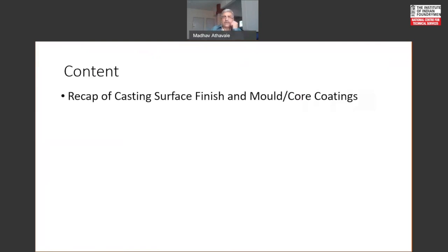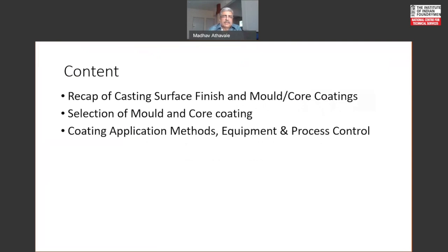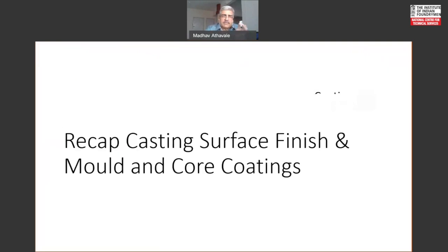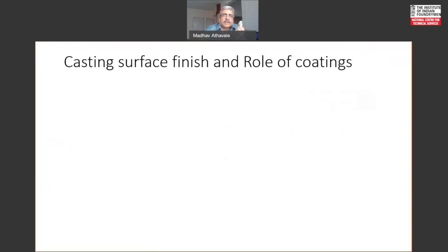We will do a quick recap of what we covered in the last lecture. Then we will look at selection of mold and core coatings, then coating application methods, equipment, and process control. Then drying of coated cores, and then we will summarize today's lecture. A quick recap: casting finish and role of coatings.